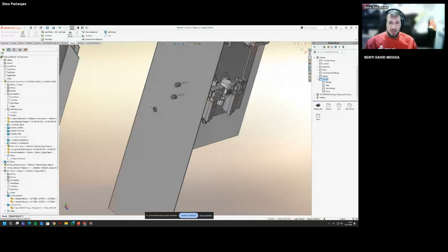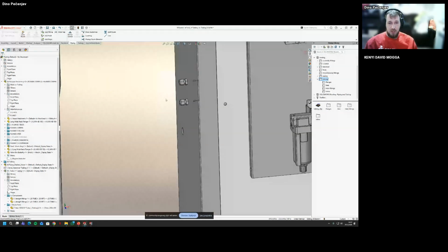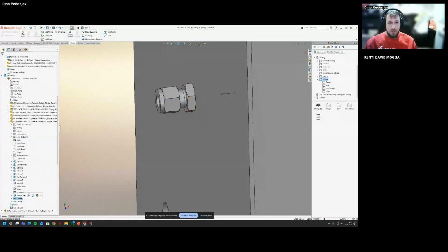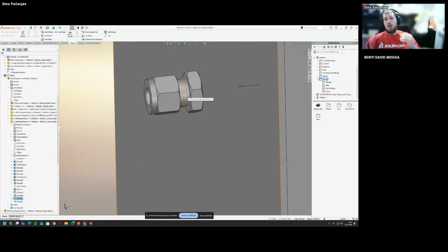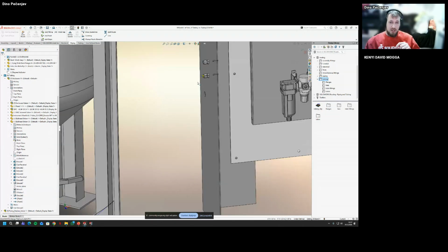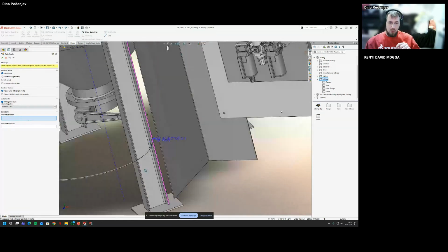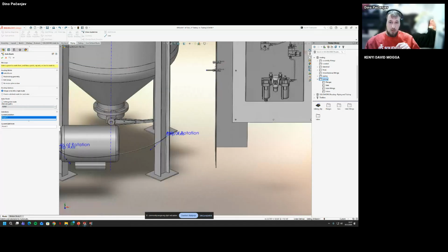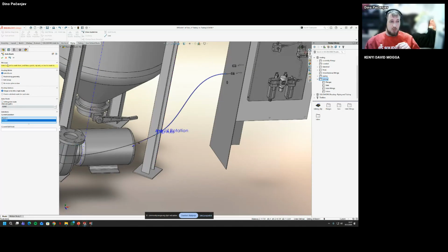And for this part, I wanted to connect it here. So we have this component. It has C points. And what is different here, I'm just going to right click on the C point and select add to route. And it will automatically create the stub. And I can just finish up this portion of the route with this part. And it's going to end it.